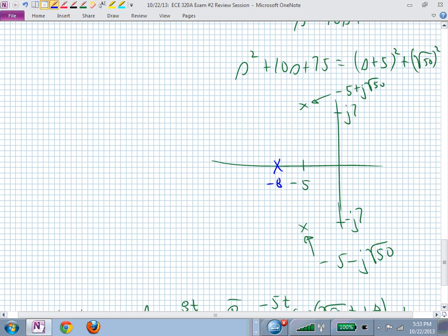So you don't want to design something like that unless you are trying to make something burn up. Because if it's electronic, it's going to go unbounded. It's going to hit whatever limits you have in your circuit pretty quickly and probably burn up. So you don't want roots there. And if you have just purely RLC circuits where your resistors are positive, not negative, you shouldn't end up with any roots over here in the right half plane. So if you do, and you're analyzing a circuit, you go, oh, I must have an algebra mistake. And I would write that on my exam.